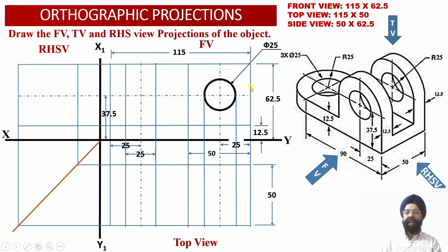Now we can check. We have got the right hand face of the solid. From the right hand side face of the solid, we have marked a distance of 50 millimeter as we move towards the left hand side face of the solid. At this distance, we have marked a vertical projector line into the front view projection, and we have extended this vertical projector line into the top view projection over here. This way, the width of this vertical web has been defined over here into the front view projection.